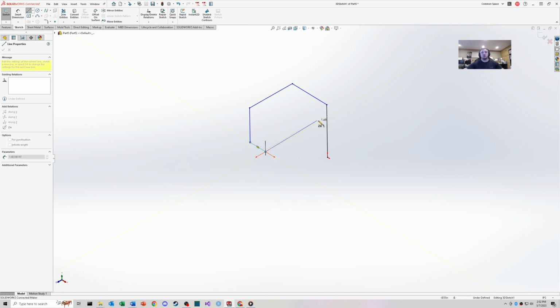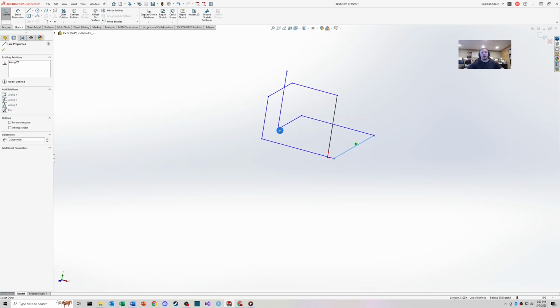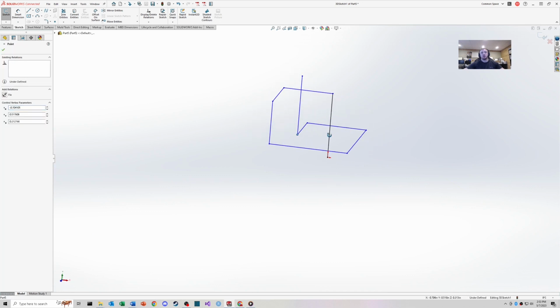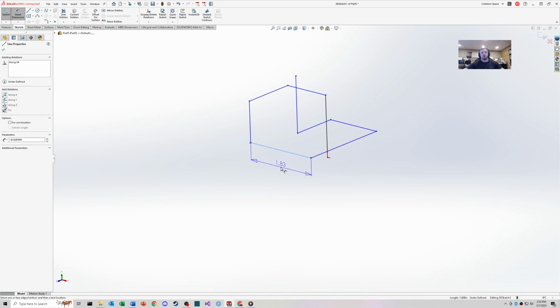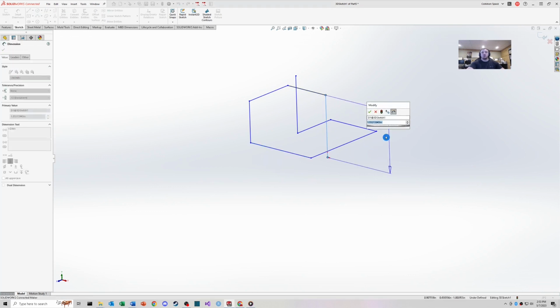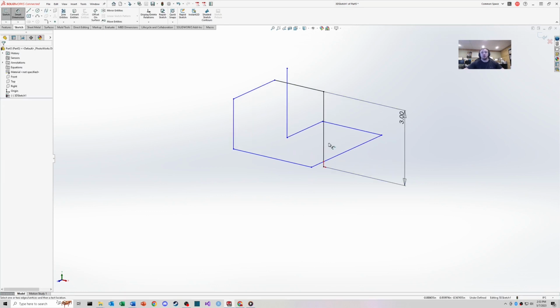Then I'm going to go all the way underneath, pass through like that, then go back out this direction, back toward us, and then hit tab to come back up. And what I'm going for is to create a knot design here, so something like that. And let's start adding dimensions. And once you get your 3D sketch generally sketched, as long as you're working with lines, it's pretty straightforward to dimension. So first, let's dimension this first line segment, and I'm going to go 3 inches, and that will scale the rest of the lines appropriately.